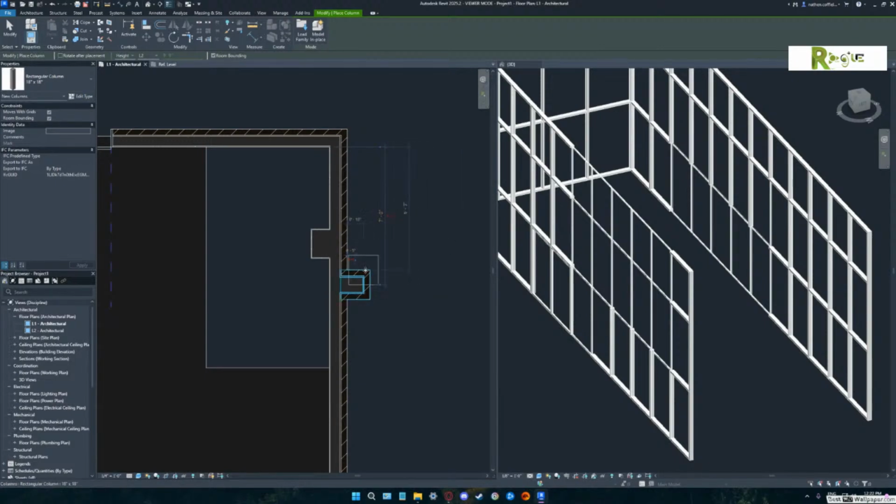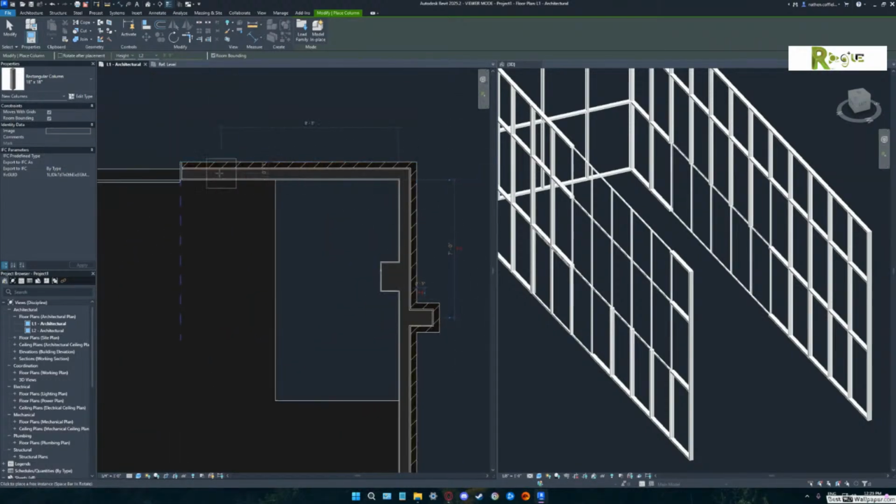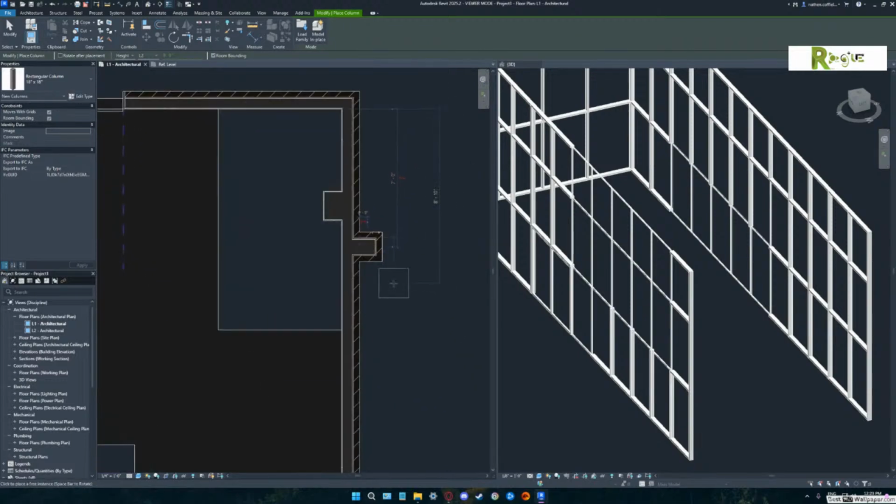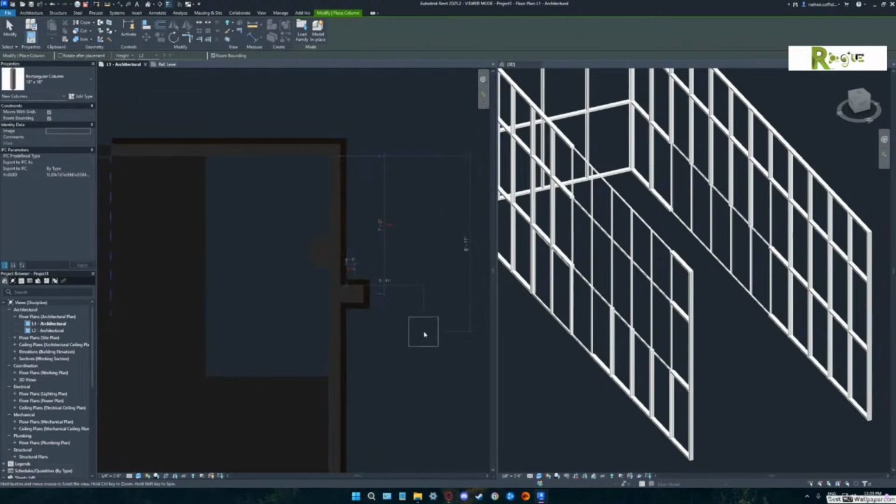Yes. Well, what would happen is if you tried to draw that wall, and people do, they get very, very frustrated because those little type walls like that don't behave well. Yeah. So that's why you've been telling me the order, to draw your wall first and then your floor and then you get your columns later. Yeah.